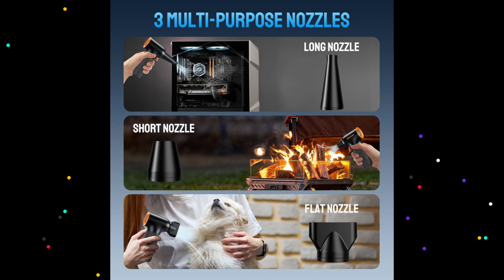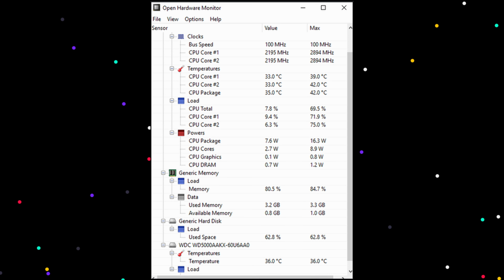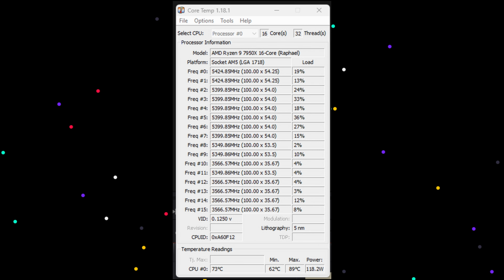After your installation, from time to time, I will also recommend that you carry out maintenance tasks on your system. For example, dust regularly. Clean dust from the heatsink and fans to maintain optimal airflow. Check your pump and ensure it's functioning properly, and listen for unusual noises. Monitor temperatures by use of software like Hardware Monitor or Core Temp to keep an eye on CPU temperatures.